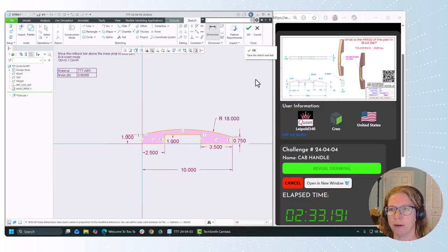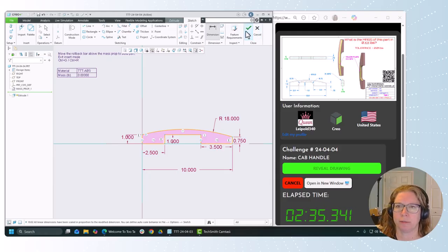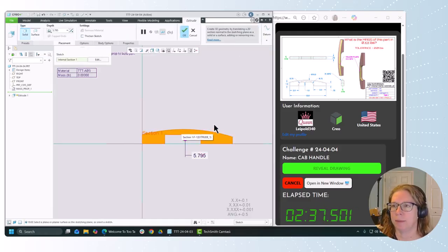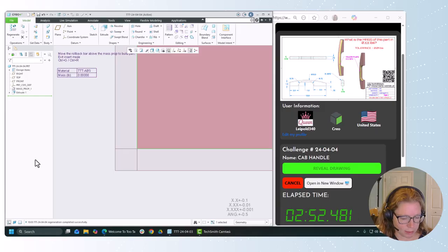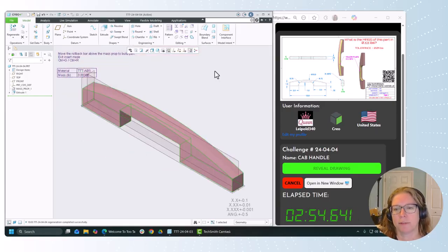Okay. So there we go. We've got all of the dimensions as shown in the front view. It is symmetric front to back. We see that in the top view with the center line, so I can pick the symmetric option. In the top view, it shows that the depth is 0.75. Middle click will finish that, and Control D will give us our default view.